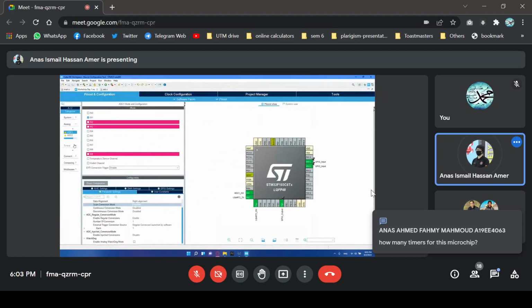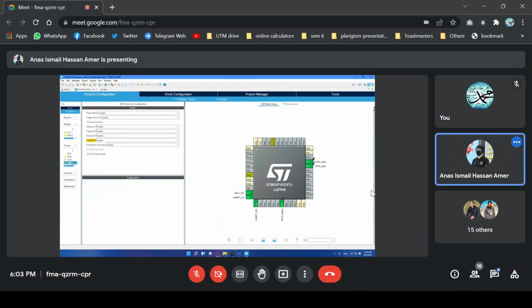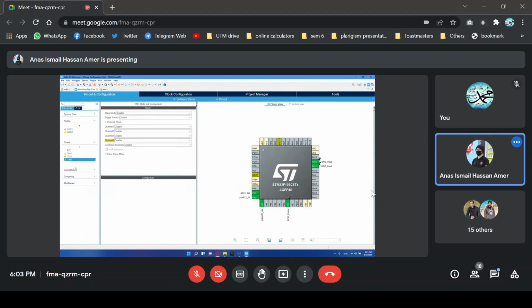So let's go into STM32CubeIDE and press on the IOC file again. And let's enable the PWM for channel 1. If you press on timer 3 and then choose channel 1, we need to choose PWM Generation for channel 1. Don't choose the no output one, since it will not have any output at the pin. We need to choose PWM Generation channel 1.